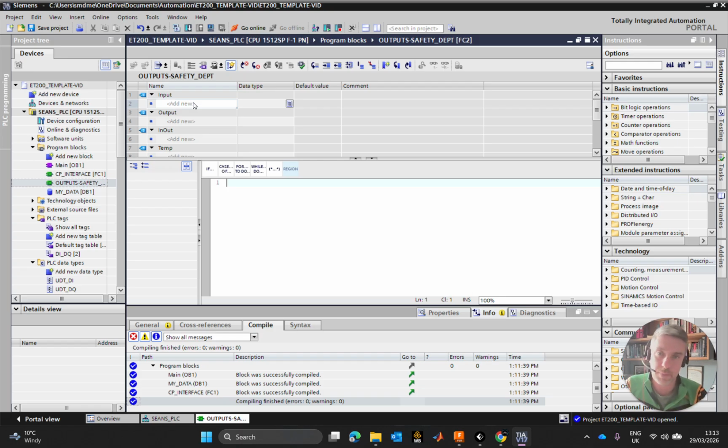You just want to drop the block off, freeze. Now you can cut the air off, absolutely, but you might also want to switch off your solenoids. Might want to switch off any sort of power going to these, and that's why I'm going to write up a safety dependent function here. In this safety dependent function, I'm going to put in all my actuators so that if the system becomes unsafe, I'm going to stop scanning this particular function.